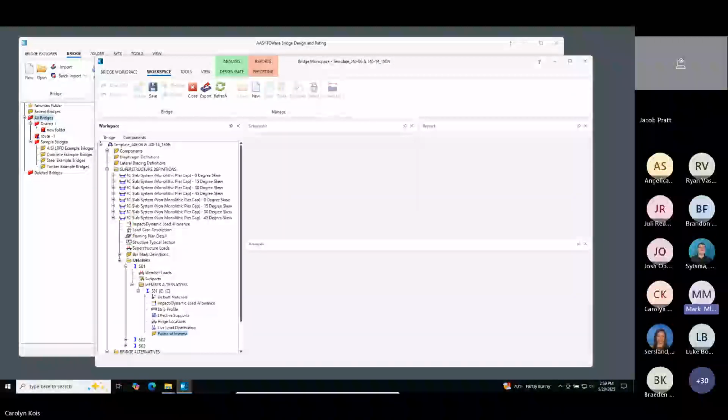The line girder was broken down into like a 12-inch slab. This one you can break down however you like. Like you can break it into 10 sections, 5 sections, 4 sections. But basically, you get to define how you want to break it down. You define the reinforcement for the entire typical section, and then it'll do an analysis of each of the segments.